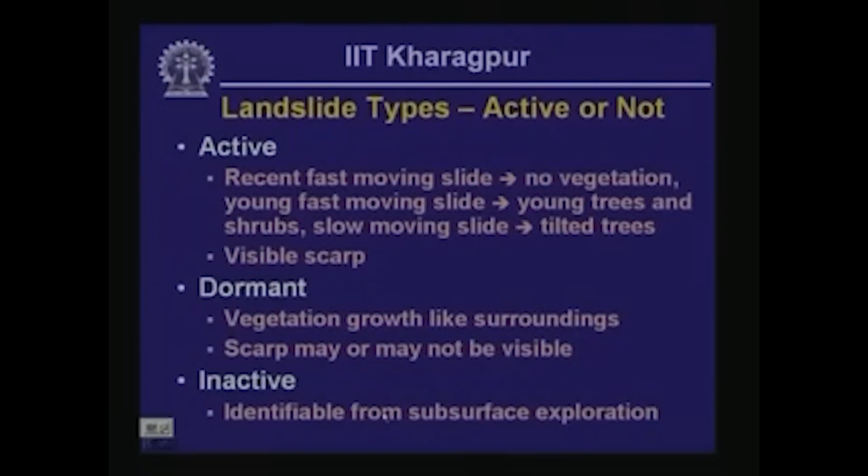Then comes the inactive landslide. In this particular type of landslide, there are going to be very few visible signs at the surface, and often an inactive landslide is identifiable only from a very detailed and careful subsurface exploration. And actually speaking, an inactive landslide is not of great engineering interest, because it has already stabilized, so it is not going to be of any consequence in construction in and around that particular area.